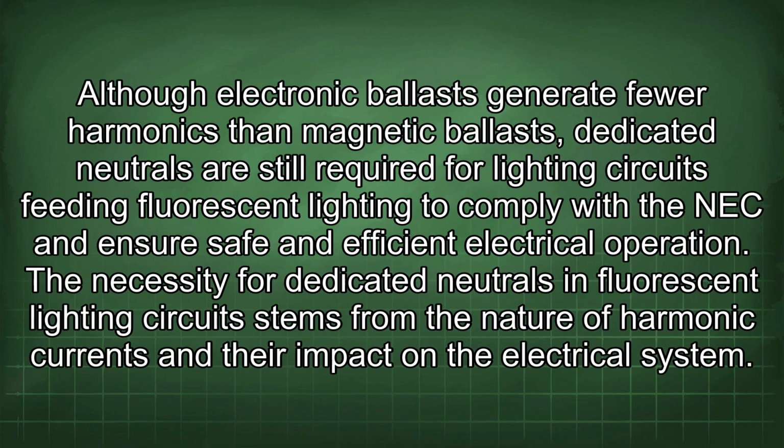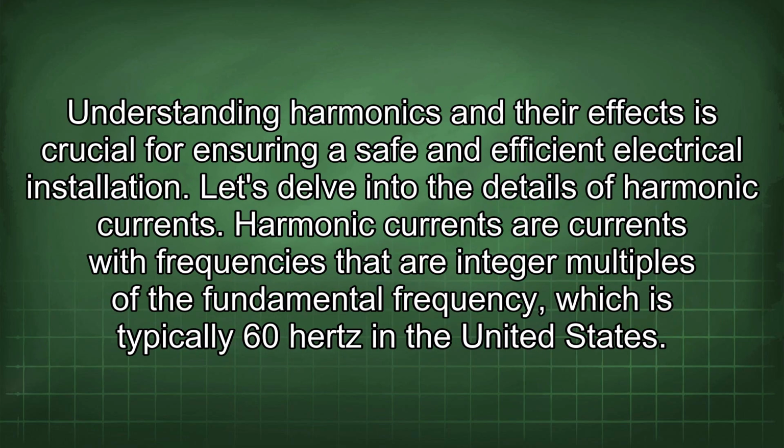Although electronic ballasts generate fewer harmonics than magnetic ballasts, dedicated neutrals are still required for lighting circuits feeding fluorescent lighting to comply with the NEC and ensure safe and efficient electrical operation. The necessity for dedicated neutrals in fluorescent lighting circuits stems from the nature of harmonic currents and their impact on the electrical system. Understanding harmonics and their effects is crucial for ensuring a safe and efficient electrical installation. Let's delve into the details of harmonic currents.